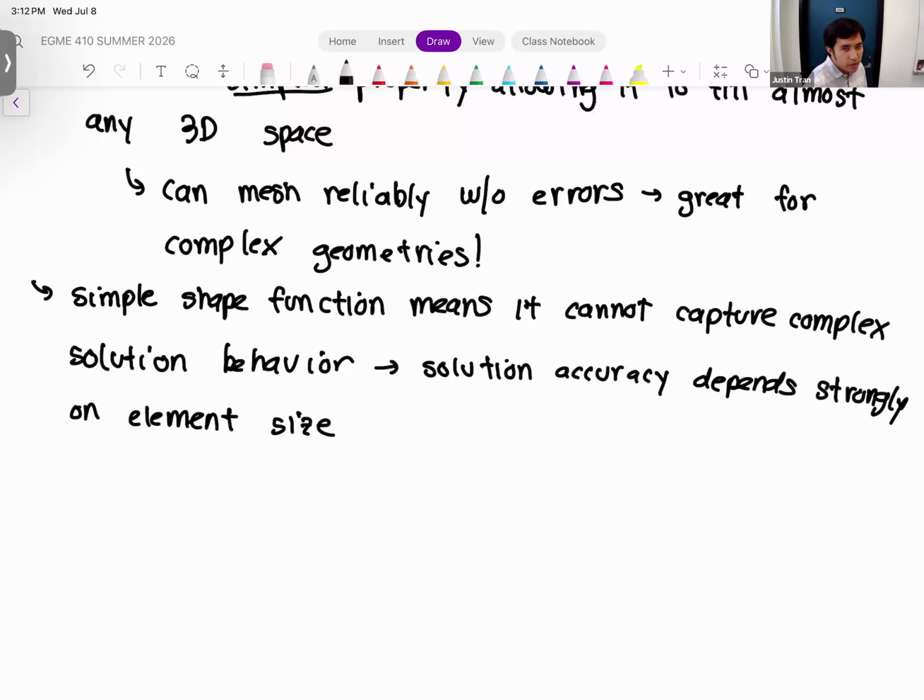But one issue that you'll run into for this class in particular with this particular license of ANSYS is that the student version or the academic version of ANSYS that you're using in the lab has a hard cap in terms of the number of elements that you can actually have, whether those elements be linear or quadratic. And so you're more likely to hit that cap if you use a linear element. Okay. But that's something that's unique to just this class. If you're using finite elements out in industry, you're probably going to have a commercial license. And so you can pump in as many elements as you want, granted that the cost of your simulation still remains somewhat feasible. Okay.